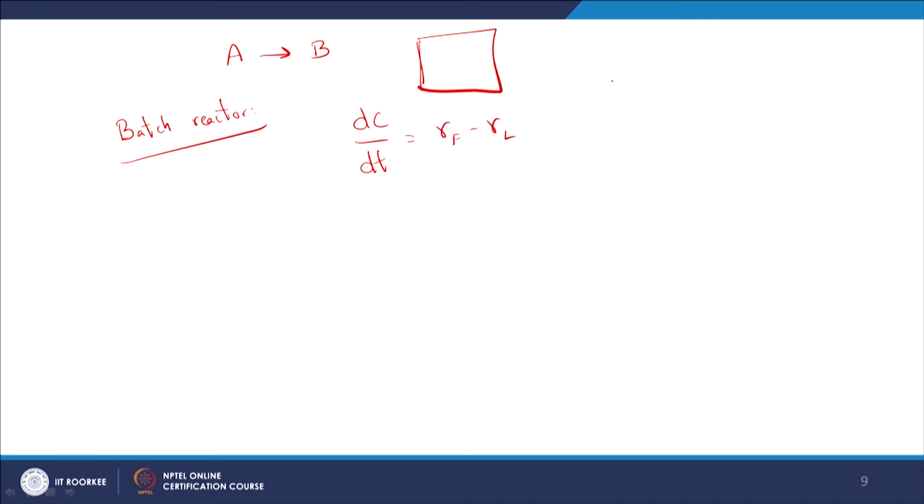And here, rate of formation of the compound A. So I am applying the mass balance on compound A, these are my system boundaries, and it is completely mixed. Rate of formation of this particular compound, what is that? It is equal to 0, it is not being formed. And rate of loss of this compound is its stoichiometric coefficient, which is 1, times rate of reaction 1, and that is equal to minus K1, the rate constant, times A.